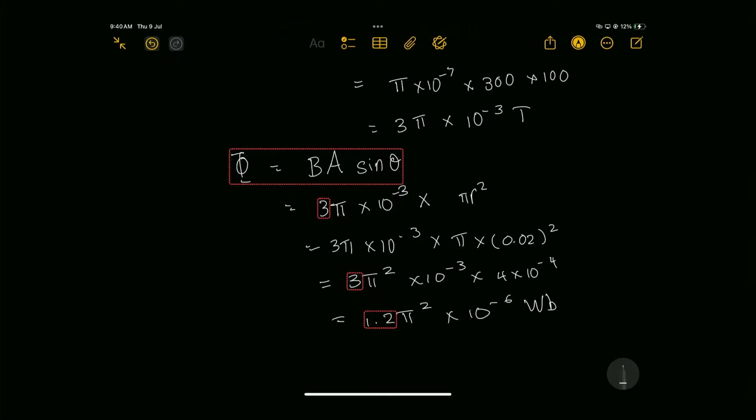Therefore, placing the soft iron in the middle of the solenoid, that soft iron is easily magnetized and also strongly magnetized in the same direction as the magnetic field of the solenoid. Therefore, when the solenoid is turned on, the iron is magnetized in the same direction, and it basically becomes a magnet as well. So therefore, the magnetic field strength of the solenoid increases by placing the soft iron core.